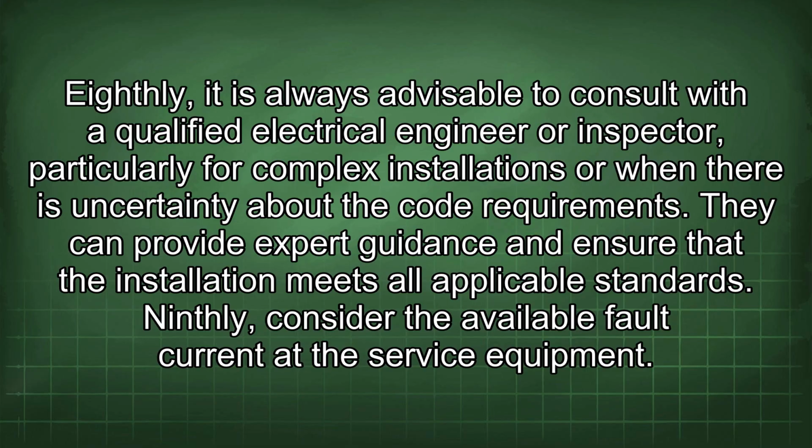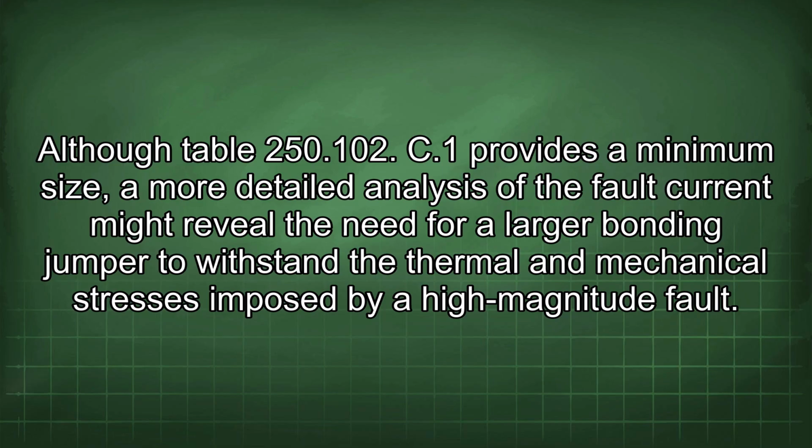Ninthly, consider the available fault current at the service equipment. Although Table 250.102(C)(1) provides a minimum size, a more detailed analysis of the fault current might reveal the need for a larger bonding jumper to withstand the thermal and mechanical stresses imposed by a high magnitude fault.